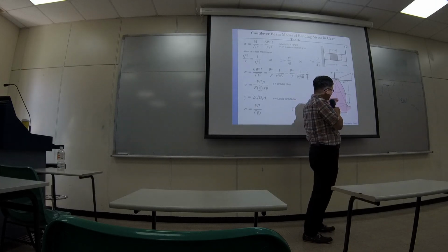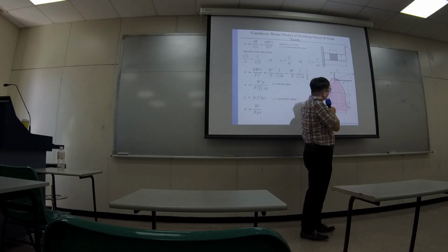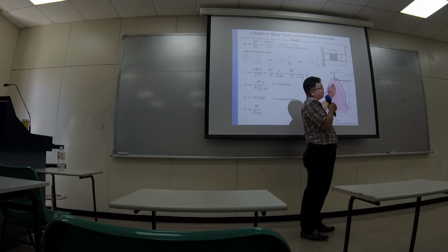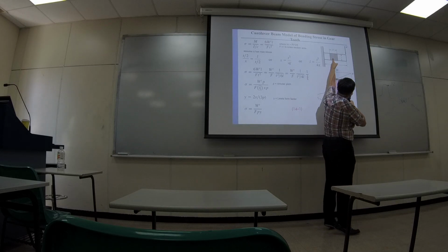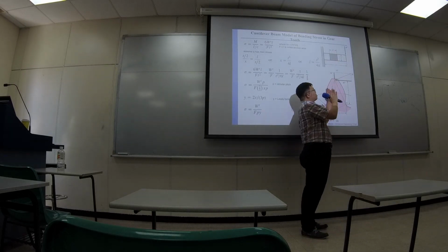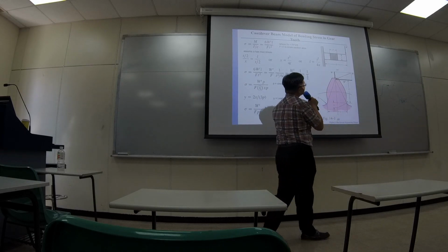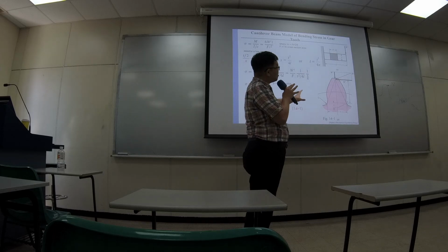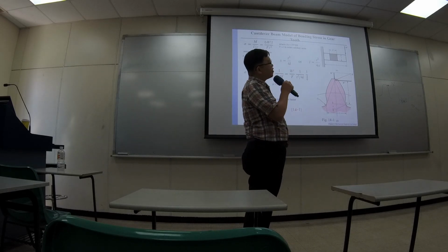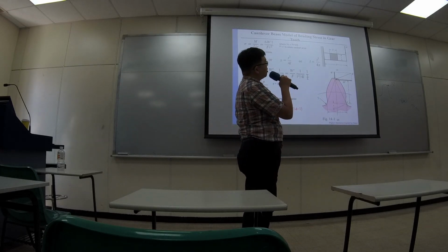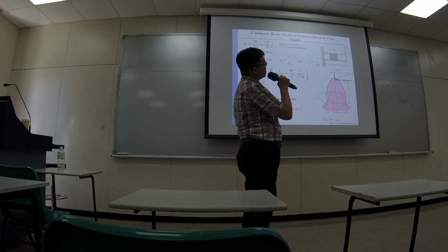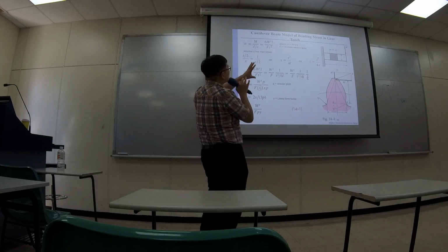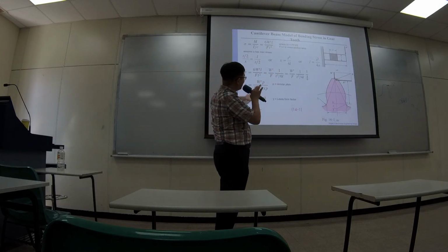Like I told you, this part is called the face. And the width along this direction is called the face width. So this is basically how thick your gear is. So he modeled the tooth profile as a very simple rectangular cross-sectional cantilever at the upper right corner. So he tried to study this whole thing in a certain way.